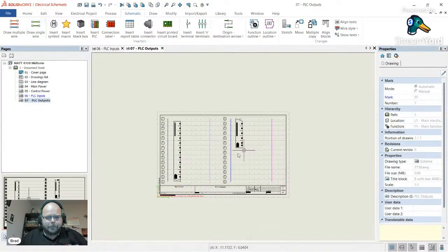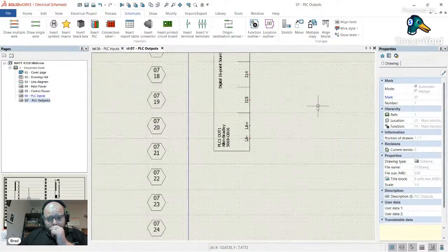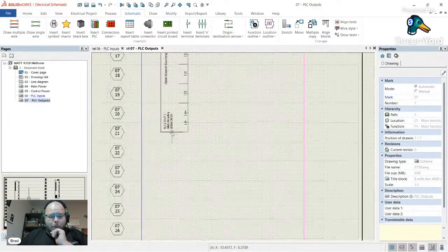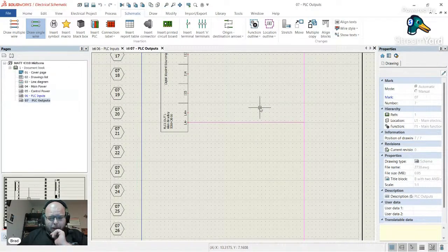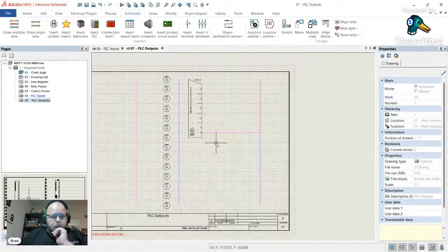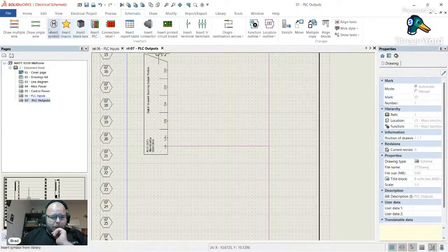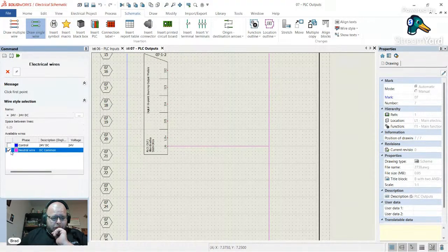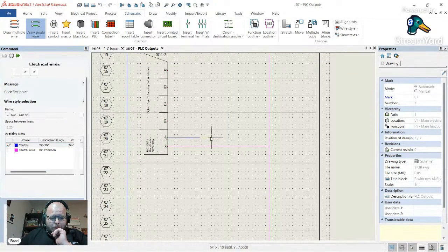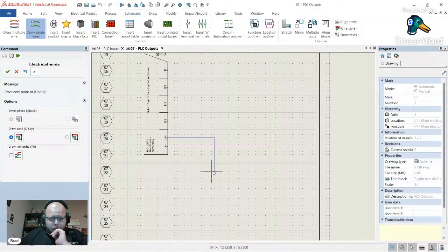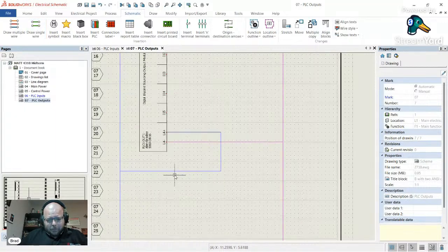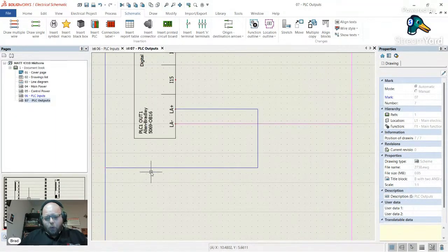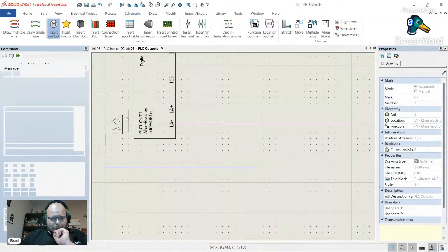One thing I would do here, we got power here. I am going to want to protect that. So let's connect the negative. We always put the breaker on the positive side when we're dealing with DC. Just like in AC, you would put it on the hot side. We use the power side. So here, here, here, and I'll drop a breaker right here on this line. And this should be, if memory serves, no more than 2 amps, if I remember correctly. Again, don't quote me on that.